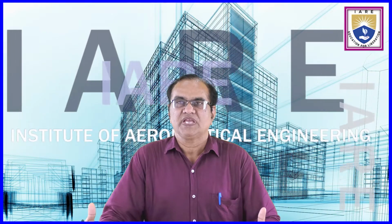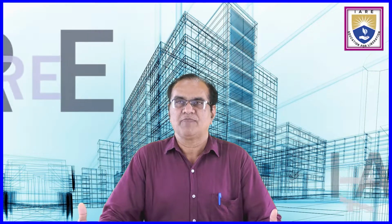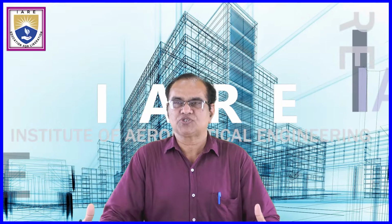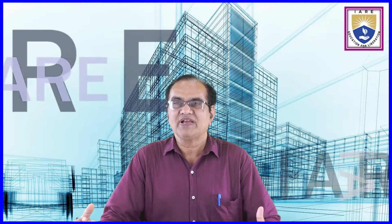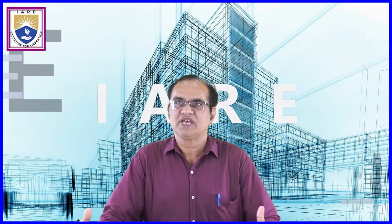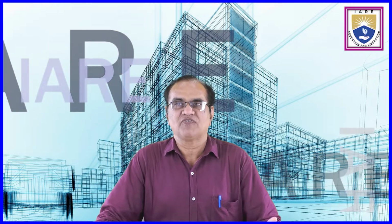In airframe system, it consists of 3 important parts of airframe. The first and foremost, one of the very important parts of airframe is the aircraft wing. Aircraft wing is used to generate the lift of the aircraft, and 95% of the lift is produced from the wing. Wing consists of the airfoil. It consists of the longerons, stringers, separators, skin. Then in the wing we have the ailerons at the tip, and at the root we have the flaps.